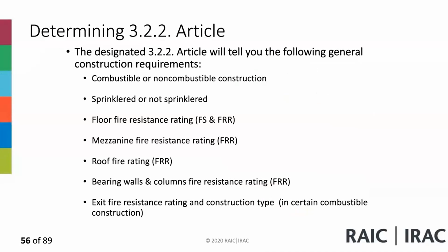The code addresses firefighting provision in terms of how many streets the building faces, and that's only relevant for non-sprinklered buildings. For sprinklered buildings, we only take a look at the building height, area, and the major occupancies.